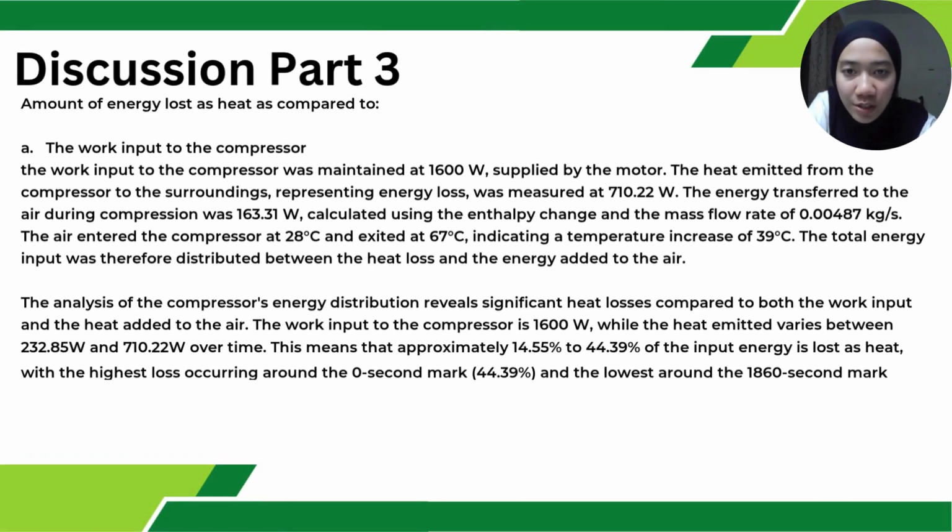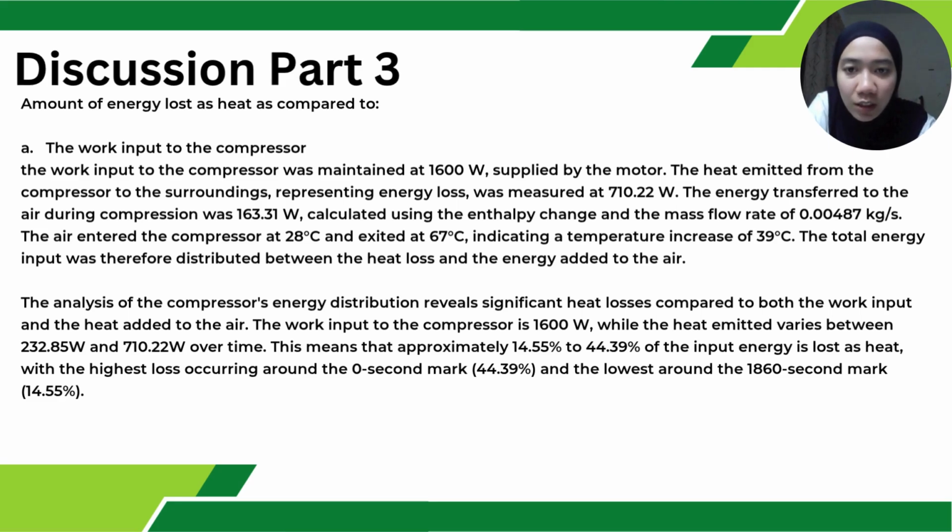Discussion part 3. Amount of energy loss as heat as compared to the work input to the compressor. The work input to the compressor was maintained at 1600 watts supplied by the motor. The heat emitted from the compressor to the surroundings, representing energy loss, was measured at 710.22 watts.